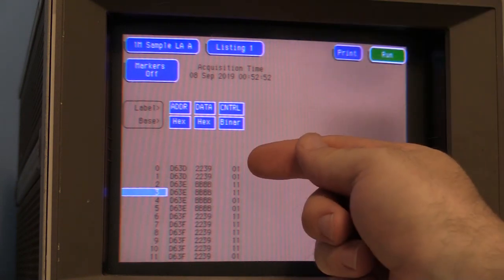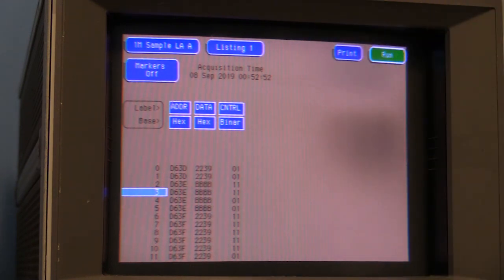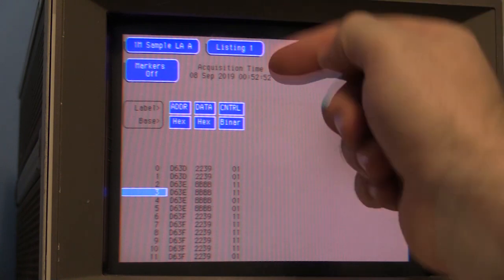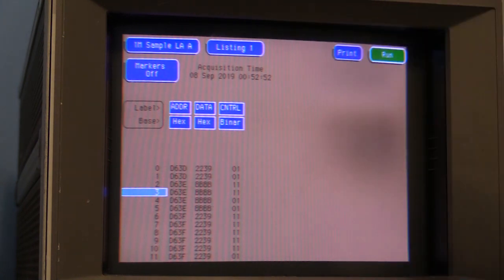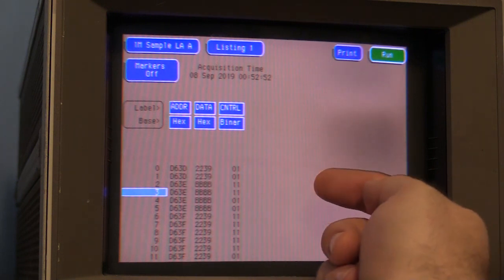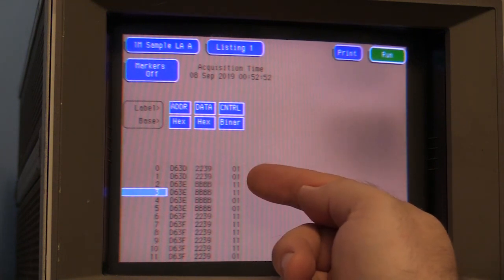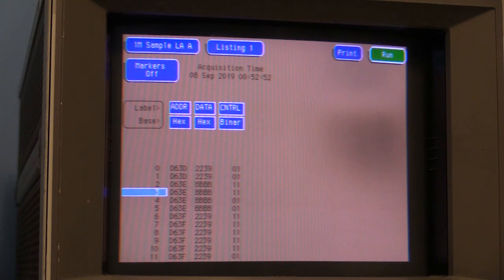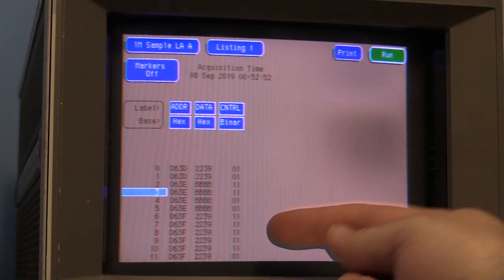In this case, the chip enable is on, but the output enable is 0. But what we really care about are just the cases where it's 1, 1. And we can see that in here, for example, it's setting 1, 1, and then it looks like it's repeating the same pattern twice on here, and that's just because the analyzer reads the data off the Sega CD faster than the Sega CD changes channels.